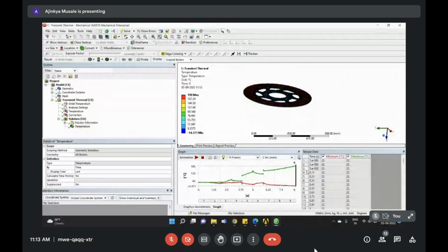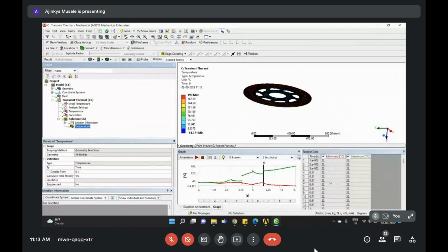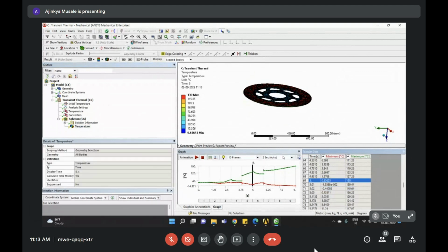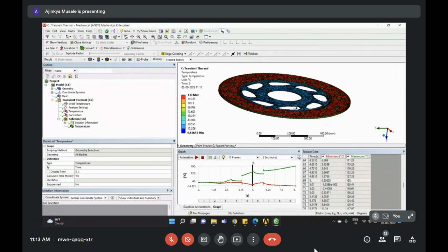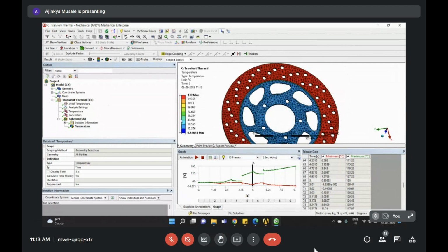And if I now want to extract results for load number 6, let's see what I'm having in load number 6. Oh, it's deactivated. So it has automatically selected load step number 5, right? So 6 is deactivated, so even if I click on 6, it has selected this 5 one. So I'll go over here and again check where I'm having my fifth load step. So right click and say retrieve the results. So it has given me results for this 130 degrees Celsius, meaning fifth load step results.